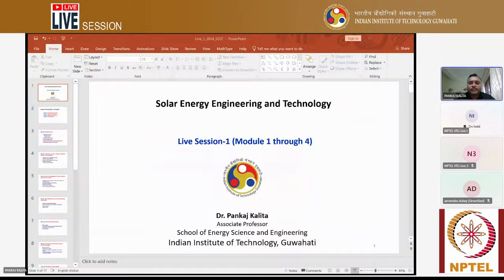And AM 1.5 we discussed at the end, because this AM 1.5 is very, very important. At this AM 1.5, solar modules are normally tested. And of course, solar radiation has to be 1000 watt per meter square, and other parameters also need to be considered.